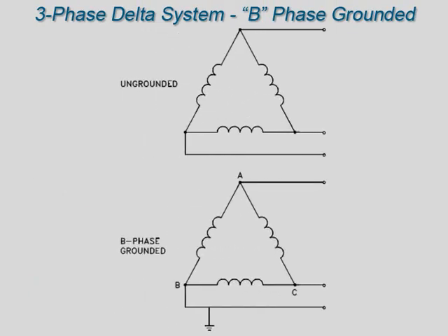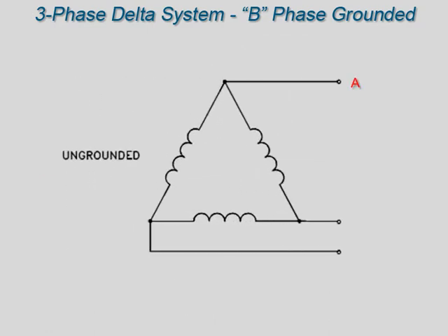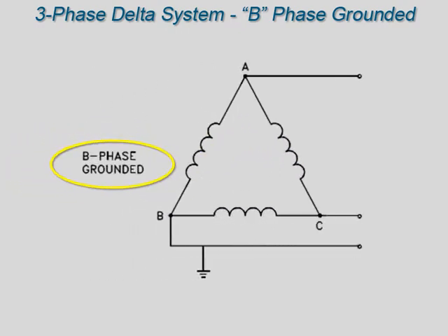The simplest 3-phase system is the 3-wire delta configuration, normally used for transmission of power in the intermediate voltage class from approximately 15,000 volts to 600 volts. This depicts the ungrounded delta, normally confined to protected environments such as fully enclosed ducts or overhead transmission lines that cannot be reached without extraordinary means. This shows a ground point affixed to one corner of the delta, which effectively lowers one phase's voltage reference to ground to 0, but retains a phase-to-phase voltage potential.